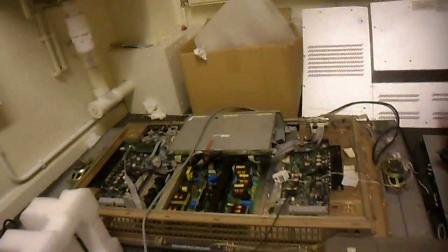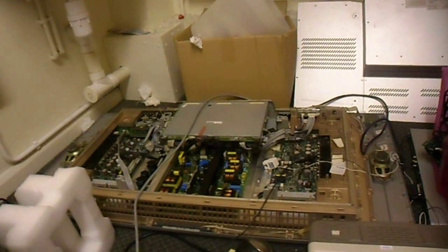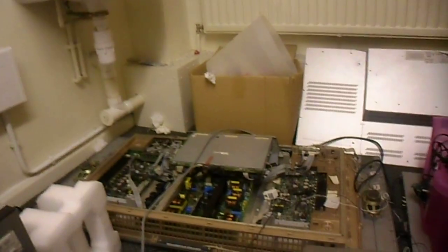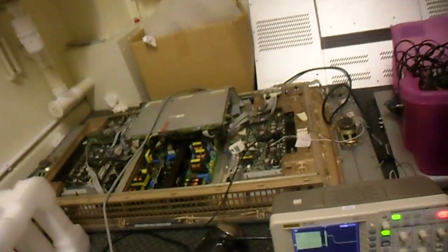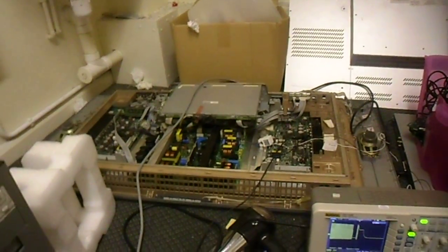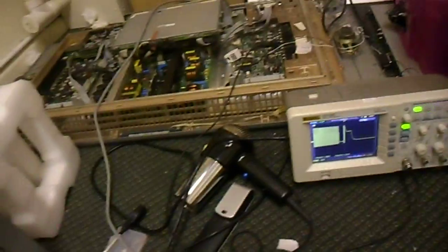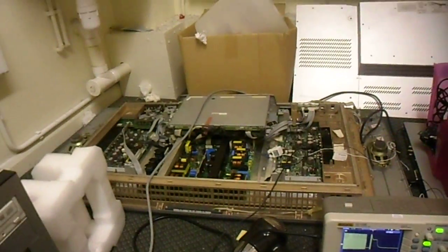I've worked on a 50-inch Pioneer, which will cut out. The VSUS will drop to about 130 volts. You can see a few pixels sparkling, but then it will just cut off because it just can't sustain the panel anymore. So that's been an interesting introduction into plasma panels and how to use an oscilloscope to measure them.